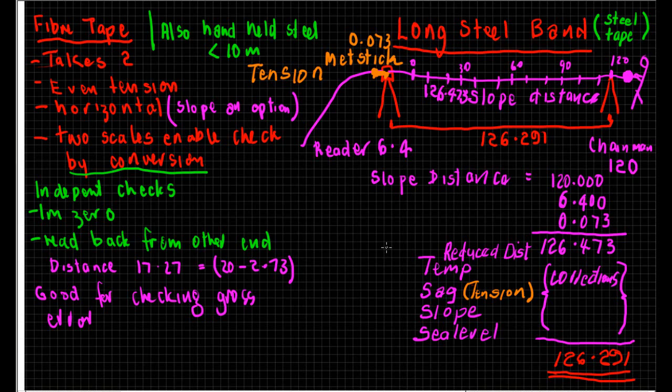Then you would measure the distance again and subtract 1 metre from it, as an independent check using different numbers, a different part of the tape. This would apply equally with your handheld steel tape, although the handheld steel tape, it must be said, can be a one-man operation, though a little bit fiddly when you're out 10 metres and trying to stretch over a drain or something.